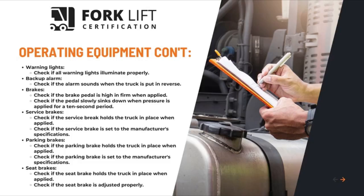Brakes. Check if the brake pedal is high and firm when applied. Check if the pedal slowly sinks down when pressure is applied for a 10-second period. Service brakes. Check if the service brake holds the truck in place when applied. Check if the service brake is set to the manufacturer's specifications.